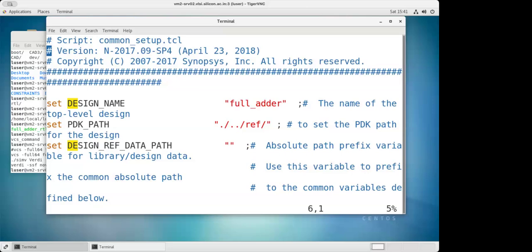Another thing is, on the synthesis side, it is very important that you provide where your libraries are present. Only then is it going to map. In that particular file, there are only three commands. But in synthesis, we discussed very clearly that it is going to map with the libraries. Now, where is that library path defined? So I mentioned there is a ref path, and inside this ref path certain files are present.